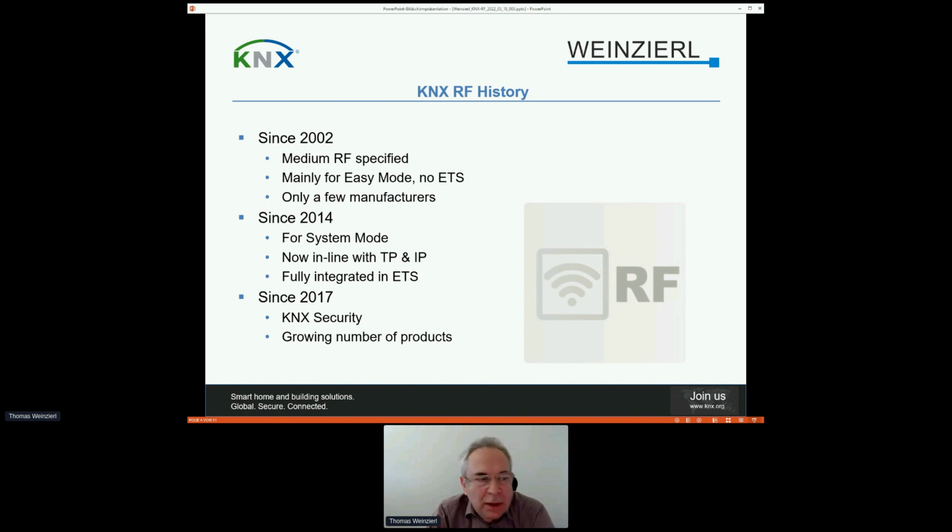And meanwhile, we come to the conclusion in the Knx community that ETS is one of the most important pillars of the system. And Knx Rf, of course, should be supported by ETS. For this, we had some adaptations, not in the medium, but in the communication mode of Knx Rf to be in line now in ETS with the twisted pair or as well with IP.